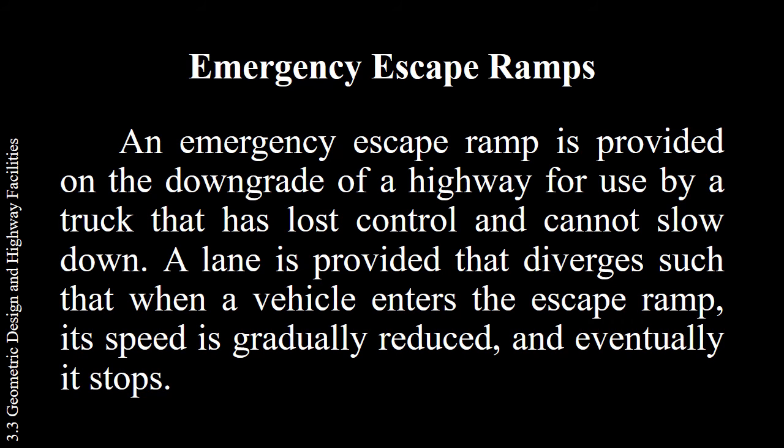Emergency escape ramps. An emergency escape ramp is provided on the downgrade of the highway for use by a truck that has lost control and cannot slow down. A lane is provided that diverges such that when a vehicle enters the escape ramp, its speed is gradually reduced and eventually it stops.